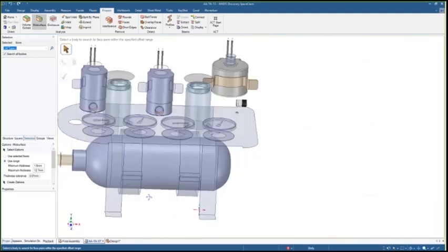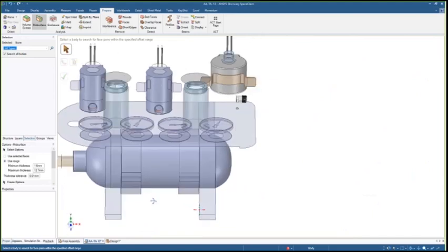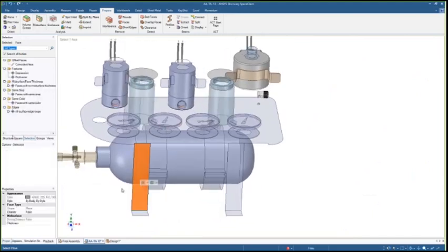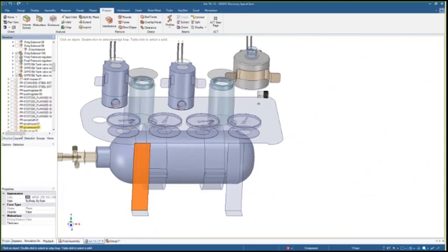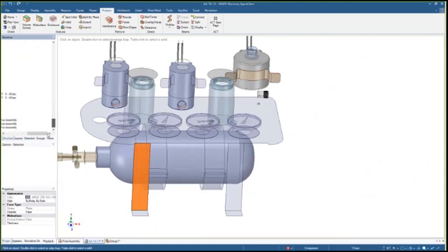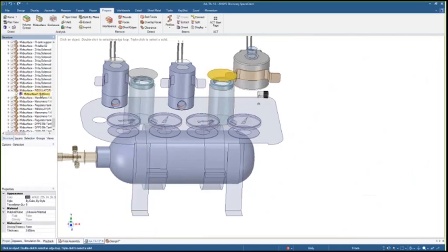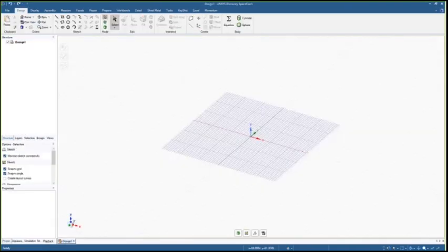And if I click in white space here, here are those mid-surface bodies. These have thicknesses as properties. You'll actually see way down in the structure tree, these mid-surface bodies right here have a mid-surface property. This is something that you can run an optimization study on through Workbench and Mechanical, and it's going to be much quicker than when you do it to a solid body.